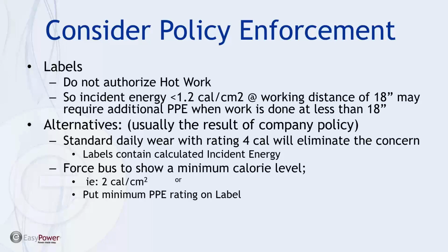Now, I want to point out, labeling and whatever's on the label does not authorize hot work. So an incident energy of less than 1.2 calories per square centimeter at a working distance of 18 inches may require additional PPE when work is done on that bus, because the working distance may be less than the 18 inches that's used to calculate the label data.